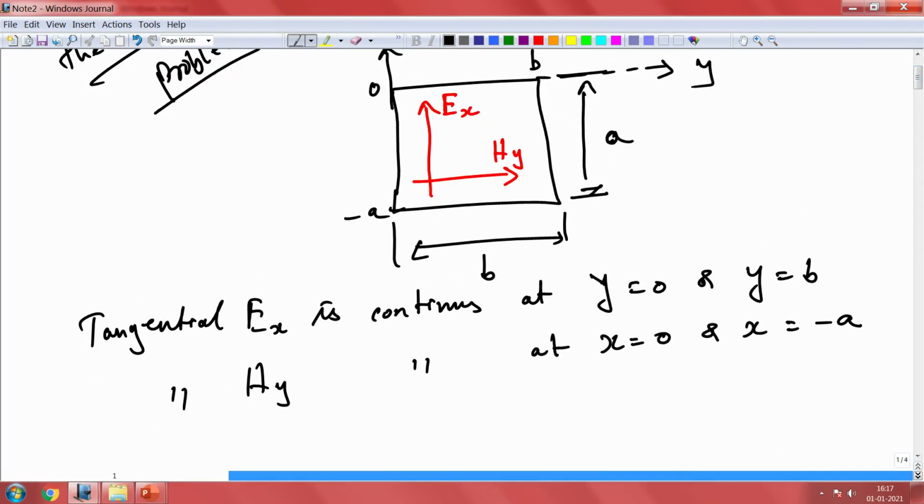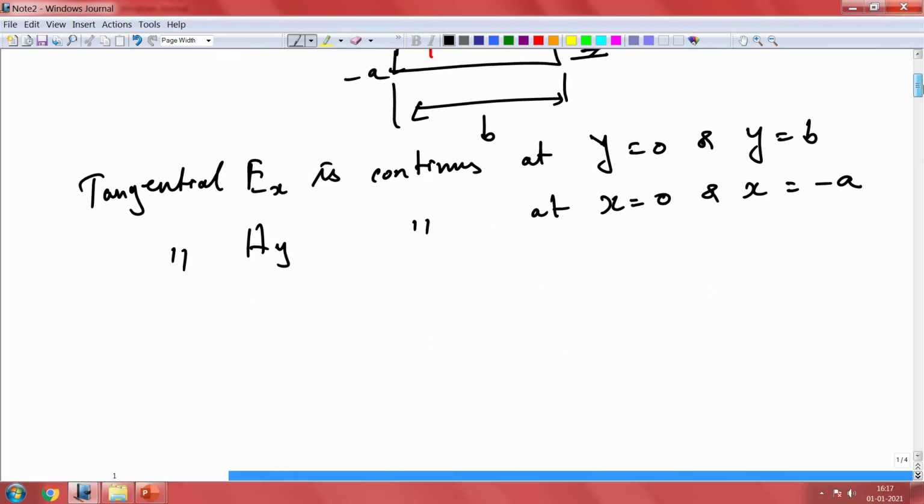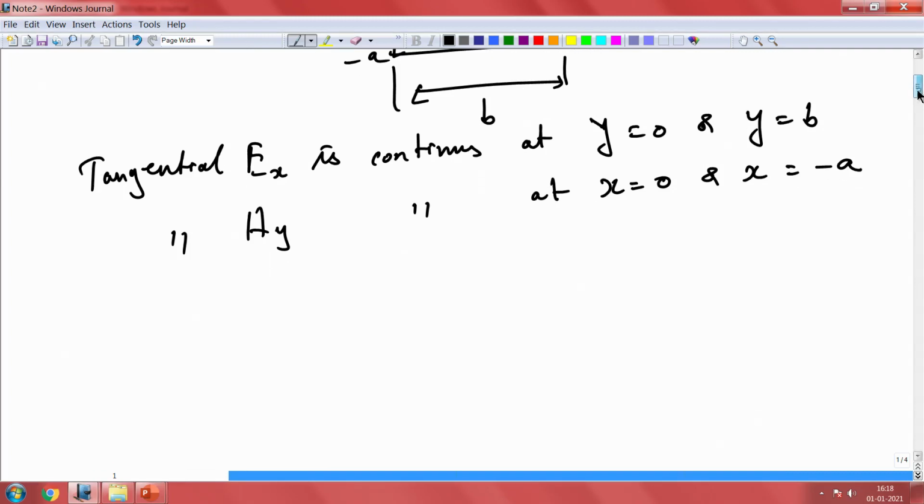If you want the energy to be transmitted through these two media, then the tangential component of E and H should be continuous in these boundaries. And the other boundary condition is automatically taken care of, right. We should also look at the continuity of D and B as well, which is naturally done here.